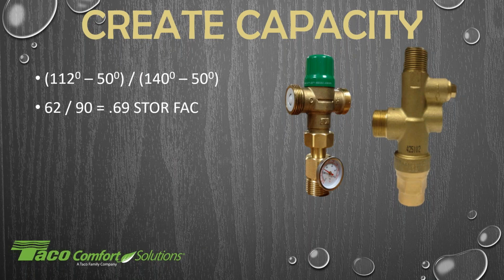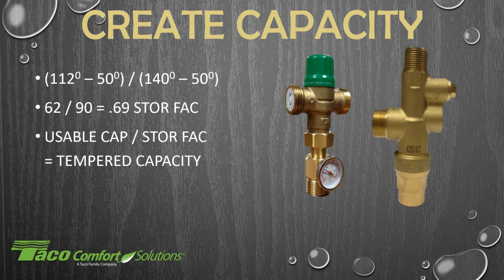So if we're using my example here of a 45-gallon tank, we're looking at about 34 gallons of usable water. Take that usable capacity, divide it by the storage factor, and we have a tempered capacity. So 34 gallons divided by 0.69 gets us to just under 50 gallons of available hot water for the house, compared to 34 gallons, by the simple addition of a mixing valve.